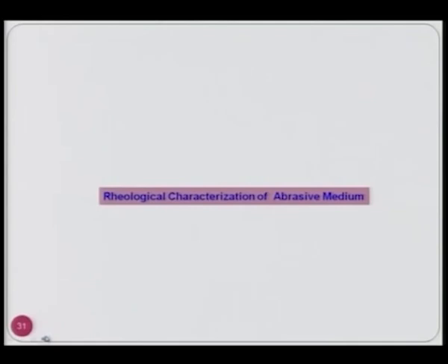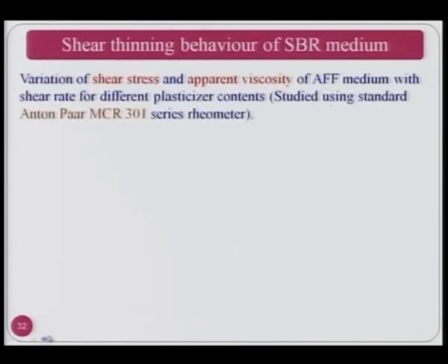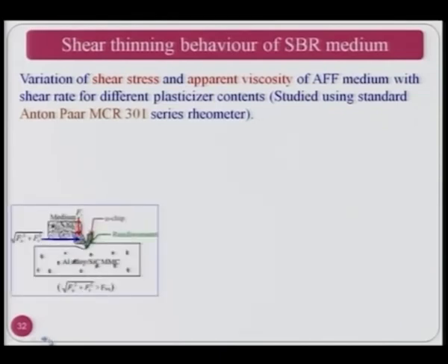Rheological characterization of the abrasive medium. Shear thinning, there is a very interesting picture here. I will show you the variation of shear stress and apparent viscosity of abrasive flow finishing medium with shear rate for different plasticizer contents. They were studied using a standard Anton Paar MCR 301 series rheometer at IIT Kanpur, and you can